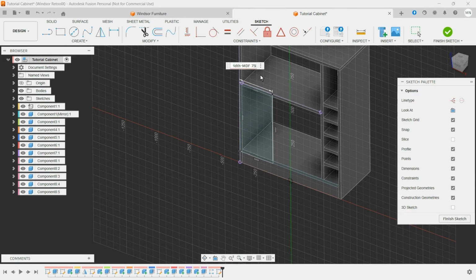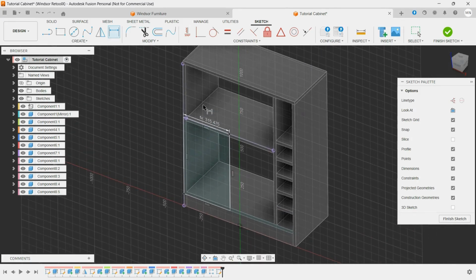And we're also going to give spacing between the two doors. For that, I'm going to put 5 millimeters, and that 5 millimeters is actually going to get divided, so it's going to be 2.5 millimeters. So we go minus 5 millimeters, type it, and then divide it by 2. So we have the size of our door.